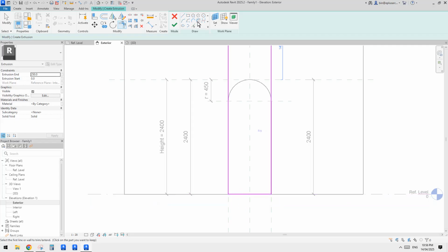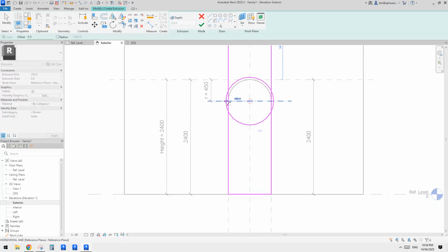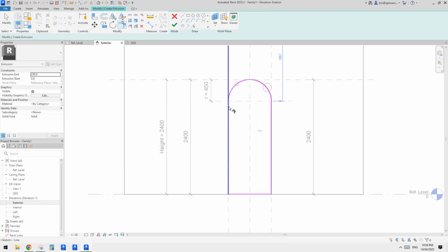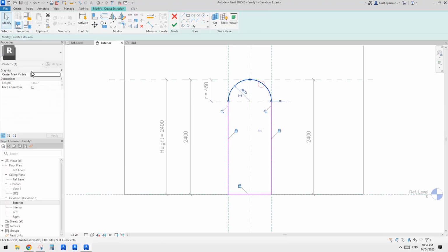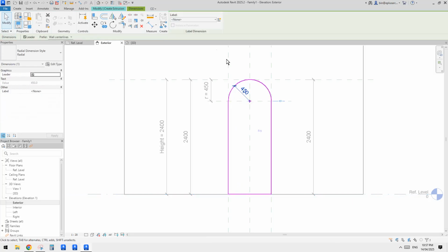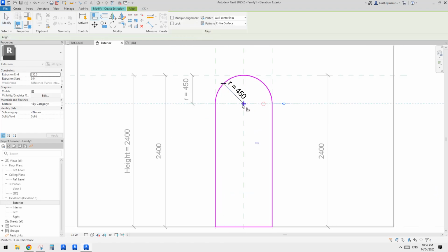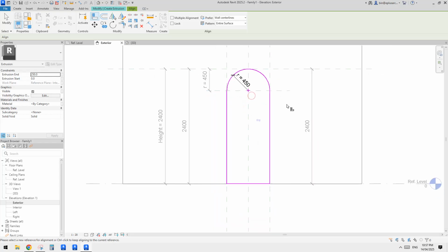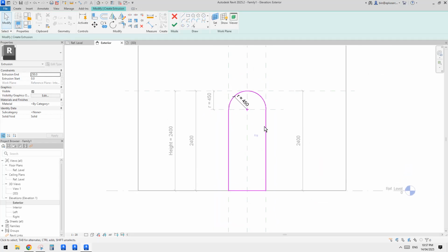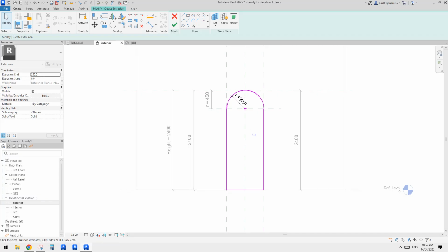And also we need a center and radius arc, and trim, select this, center mark visible. Also turn on add a radius, so link that to the radius, and also AL, lock onto this reference plane. So now there's no more blue color dimension anywhere, which means it's all good.